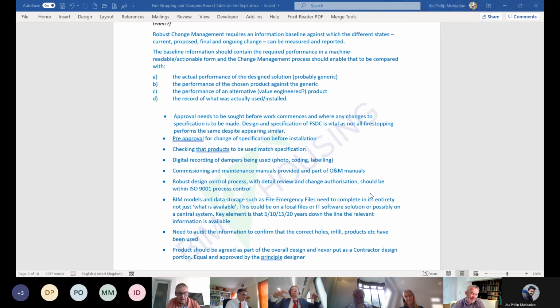And you look at it and you go through, okay, we're going to change the damper to another one. Another one comes in at part 2. The problem is the damper's the wrong damper anyway. In the spec, it's the wrong damper. Fundamentally, it's not right. Like I've got an AOV system. I'm not going to say where it is, but essentially it's a motorized AOV pressure differential system. It's a silo door. I'm going to them, it's not right. It should be a damper. And they're going, well, why? Because you specified a part 2, part 4 system, but you put a part 2 component on it.